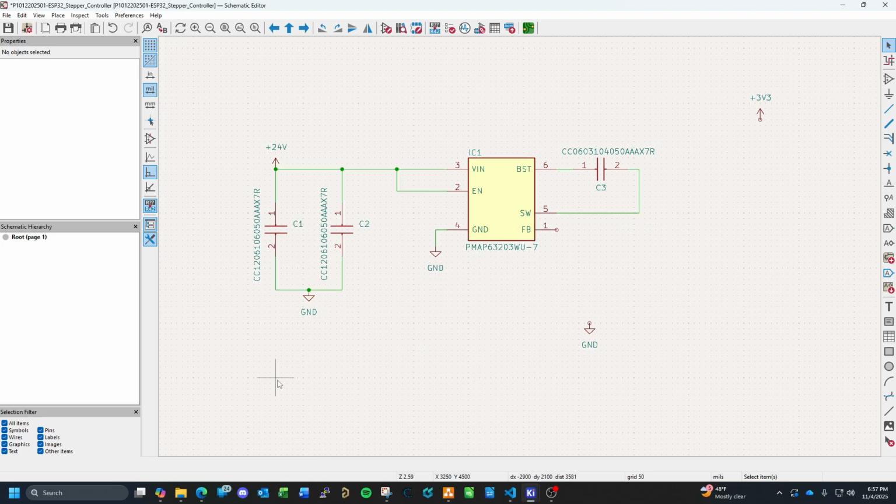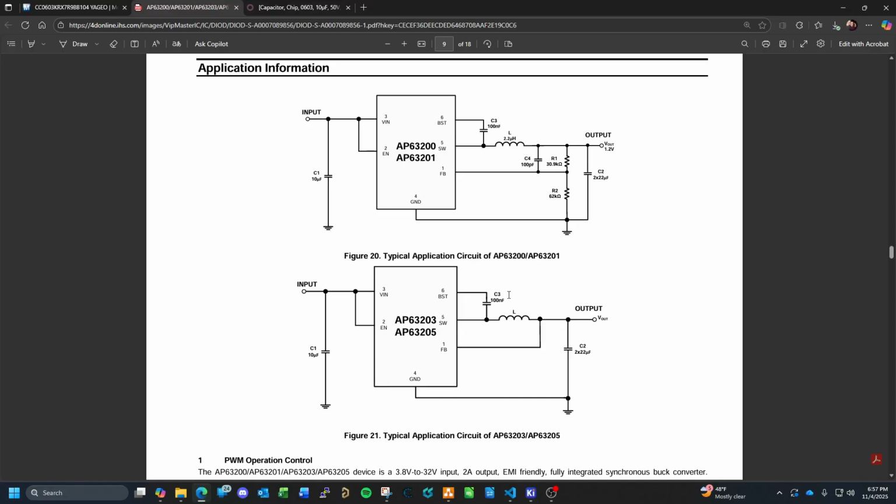All right. So out of that recommended schematic, what would be left to do? So we're going to need to get the inductor and the output capacitors, basically the bulk capacitors. Those are 22 microfarad, but we can get them at a lower voltage, like 6 or 10 volts. That should be fine because we're only at 3.3 volt. But we could go with larger. See what we can do at 22 microfarad.